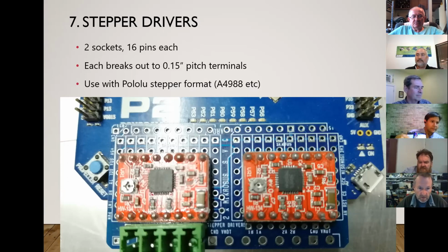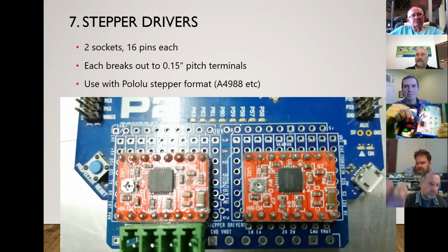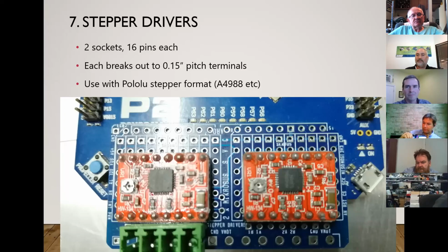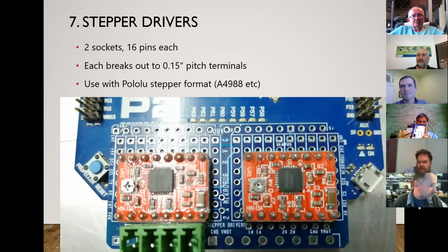Last spring I bought a bunch of these super cheap from Amazon. These are the OLED ones using I2C, and I was able to hack John McPhail's I2C driver code for Spin 2 to get this to work, just bare bones, hello world type stuff. But I think there's some SPI versions available. There's some that have 3 colors. I think Parallax carries the 3-color one. But this one here is probably like $4.